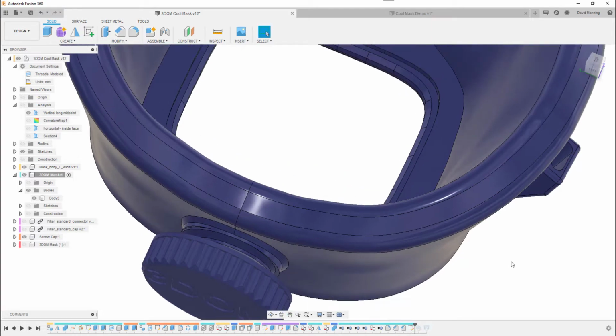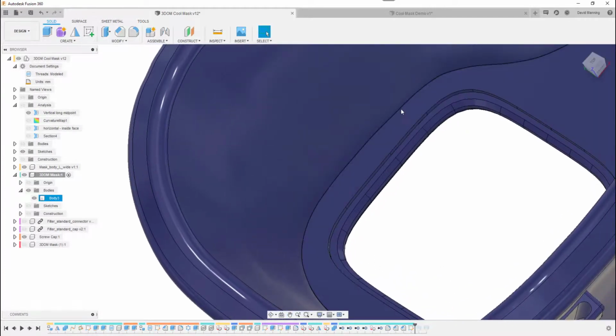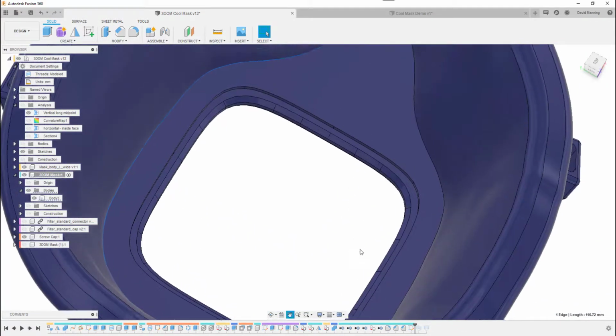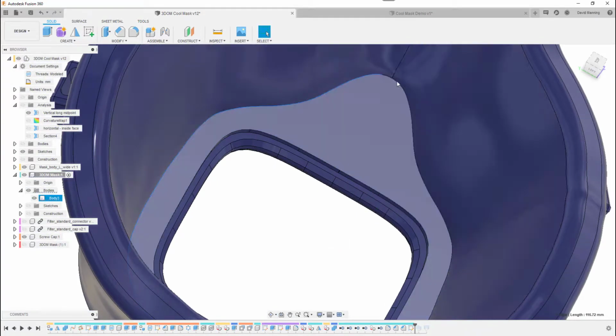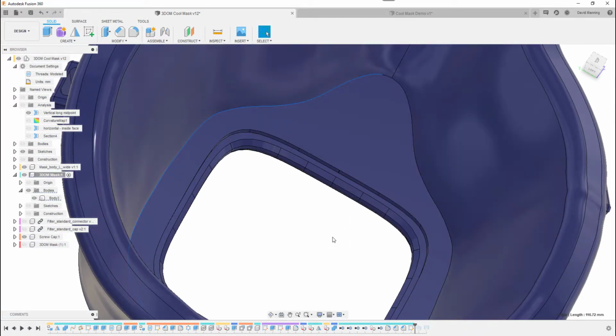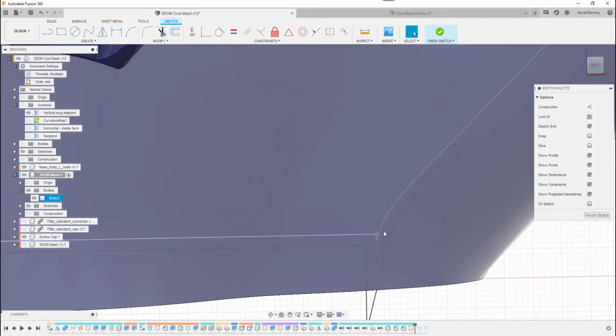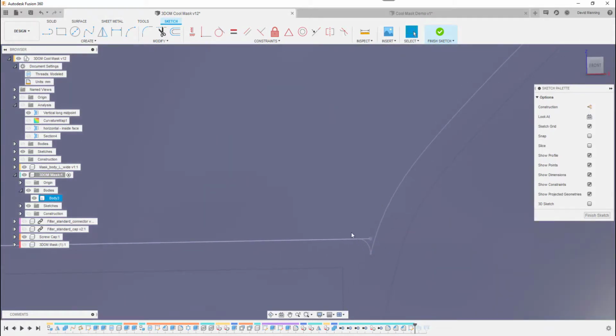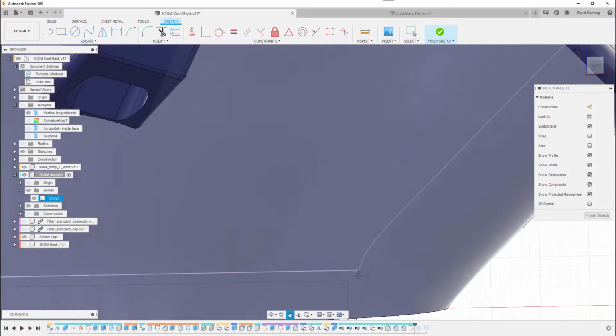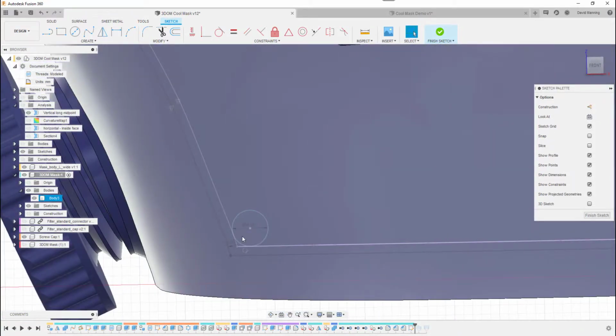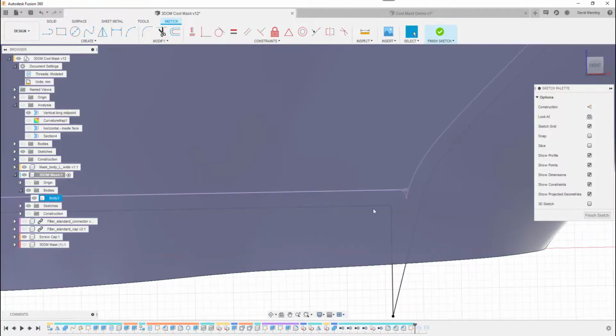Now the last thing I tried to do on the inside here, I wanted to replicate another fillet. If I tried to fillet that, it just didn't want to work for me, and I wasn't happy with the way it worked. It was all to do with the interfaces here, ultimately probably to do with the meshes and just the finite detail not being quite right. Ultimately you're not going to be able to see anything, so what I did, I drew a sketch, and if we edit that sketch, I've just bisected it there on the plane, and there's some weird things going on there with that sketch line. But what I was really interested in doing was producing a radius in here. Now I'm not sure what's actually happening there. So that's an artifact of why it's not going to fillet for me.